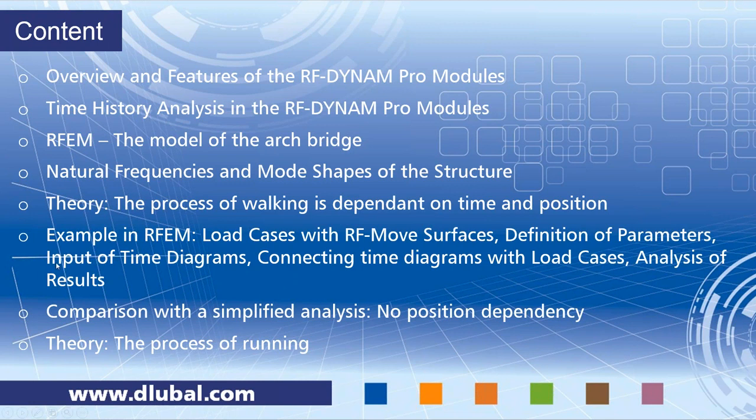We will input time diagrams, and we will use a still quite new feature, the direct input of function terms, where you can use the parameters that you have defined. And we have to connect the time diagrams then with load cases to define the position of the excitation cases. And of course, we will analyze the results and study this.